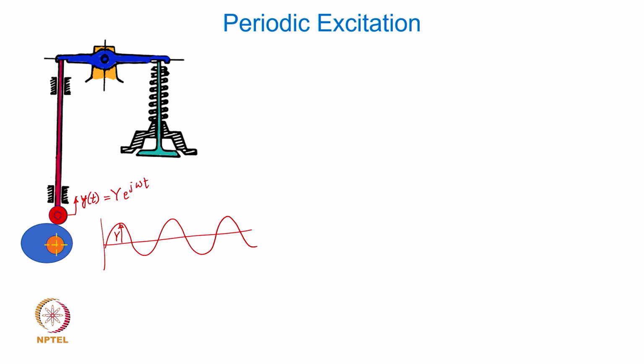Now, this is very important, let me tell you, and you will realize shortly why we made this assumption, despite the fact that many times the cam may not have a harmonic profile. You already have learned in your kinematics and dynamics course that a cam profile can have different forms, right, and the form is essentially guided by its intended dynamic characteristic of the cam follower mechanism.